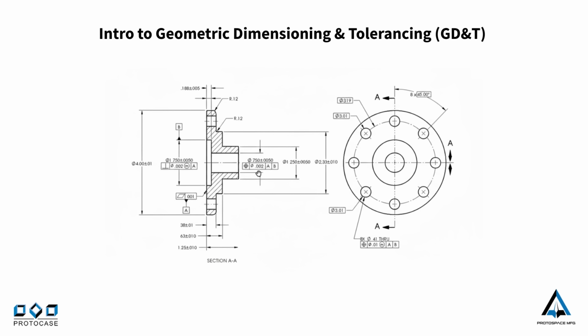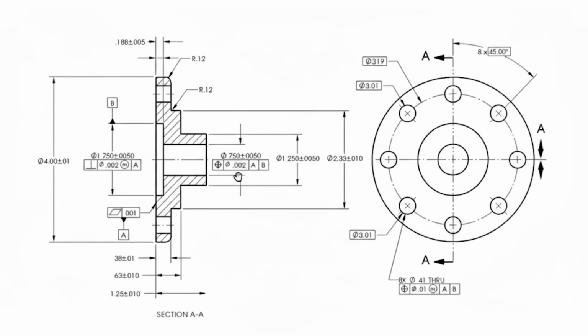So let's look at the drawing now with some GD&T applied. You can now see that GD&T ensures that the functional requirements of the assembly are transferred down to the individual parts. Universal symbols such as flatness, perpendicularity, etc. are placed on the drawing to reduce the writing contained in the drawing itself. Now generally, when applied correctly, GD&T ensures that functional features not meant for printing are kept separate, maximizing productivity while also maintaining the intended form, fit, and function of the design.